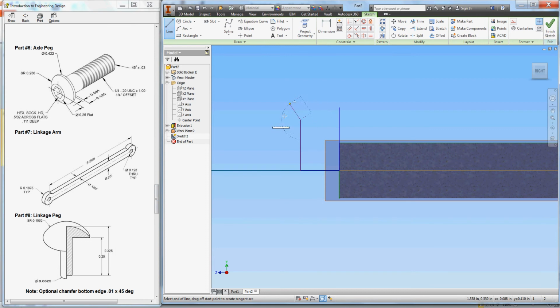I'm going to right click and go to Slice Graphics and scroll into that part. Anytime you click on Slice Graphics, you have to click on Project Geometry. Project Geometry. Zoom in a bit, pick this up, pull it to the back. Now, I'm going to create a shape that represents the revolve of the peg. Make sure that's centered.